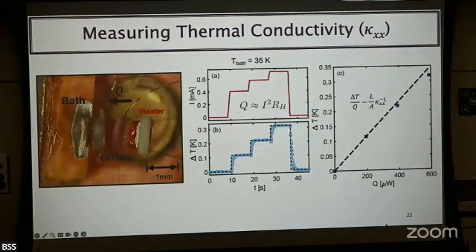What happened here is that down here we have no heater or whatsoever, so the hot thermometer and cold thermometer are at exactly the same temperature. Then when we turn on the current, a temperature gradient starts building up. This is a transient, right? Once heat starts coming in, it immediately gets heat; it's still cold, but then heat current starts flowing and leaving the sample.